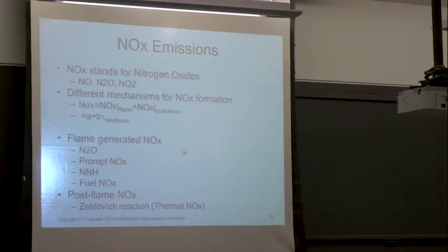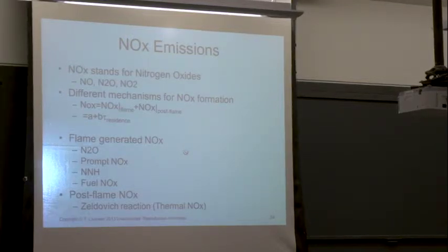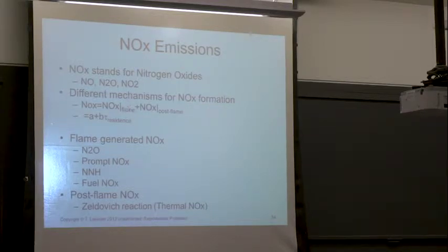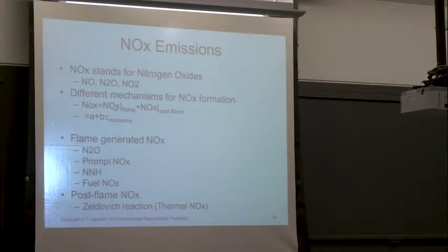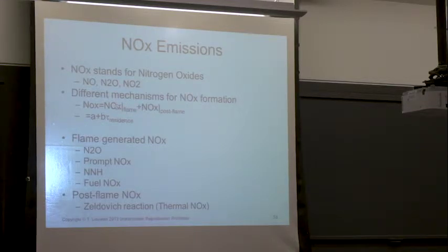First, if we talk about NOx emissions, NOx stands for nitrogen oxides. So we have NO and N2O and NO2. And obviously there's an enormous amount of really interesting kinetics that goes on with NOx chemistry. But from a zeroth order, you can think of flame NOx and post-flame NOx. You have NOx that's formed where the fuel is actually reacting with the nitrogen in the air to form NOx. And here I'm talking about systems where there's no fuel-bound NOx, where the nitrogen is in the air.